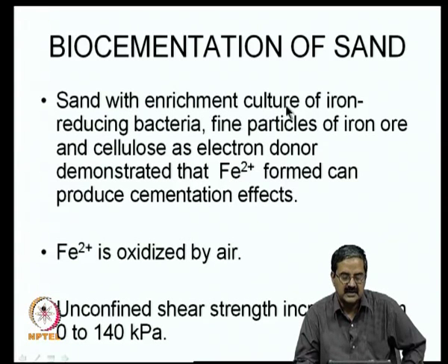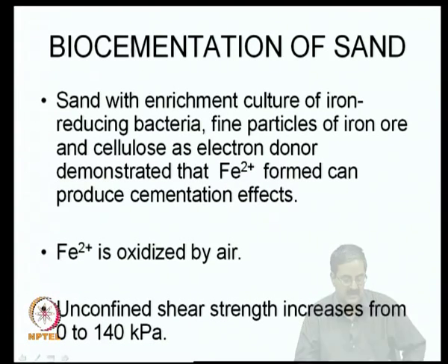Sand enriched with a culture of iron reducing bacteria, fine particles of iron ore and cellulose as electron donor demonstrate that the Fe+2 form can produce cementation effects. In fact, they noted that the unconfined compression strength can increase significantly, by a big number.